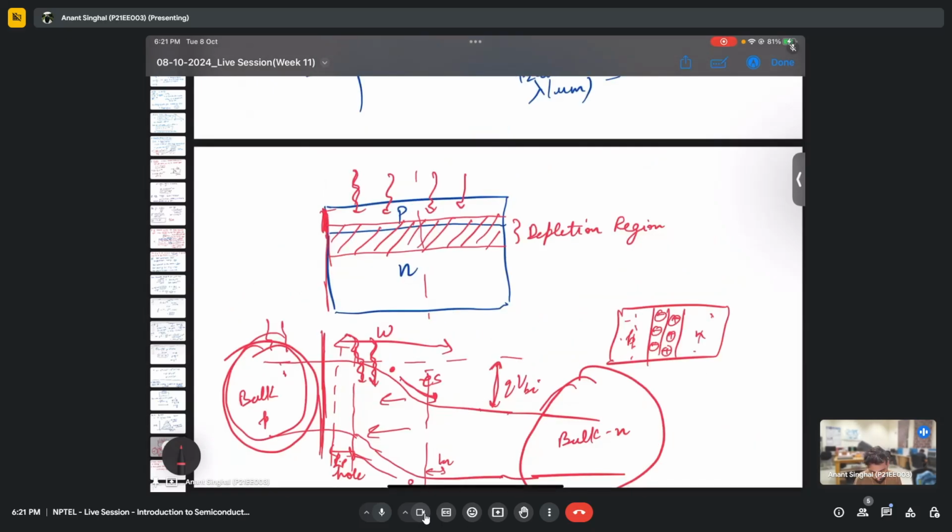Now, apart from keeping it thin, if we have this thin, then the depletion layer can also be a concern, and also the resistance of this thing. I guess you have heard the term sheet resistance. So if we have a very thin layer of this P, we will have a very high sheet resistance, and once we make some external contact, a lot of voltage will be dropped in the sheet resistance only. And in order to reduce the sheet resistance, first of all, we make the P layer very heavily doped.